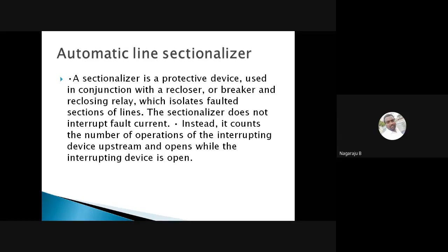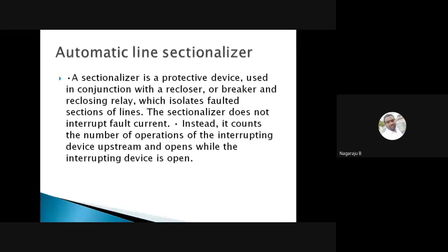The first one is, if the fault is cleared while the reclosing device is open, the sectionalizer counter will reset to its normal position after the circuit is reclosed.